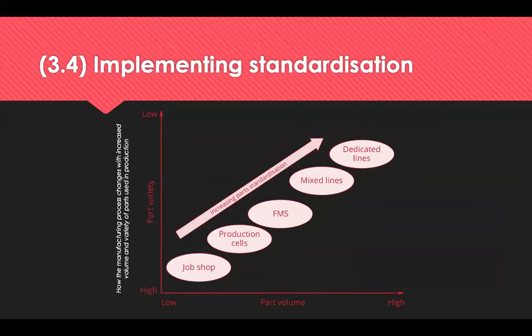Standardisation can be implemented at 3 levels: product, processes or production, and parts. Product standardisation means no variations, which results in longer or unbroken production runs, reduces costs, reduces the complexity of the operation in terms of the production process for products or services, and helps to improve quality as there are fewer products and fewer components to deal with. The process or production method of standardisation allows batch production or even continuous manufacturing, which reduces the unit cost compared with a job shop.